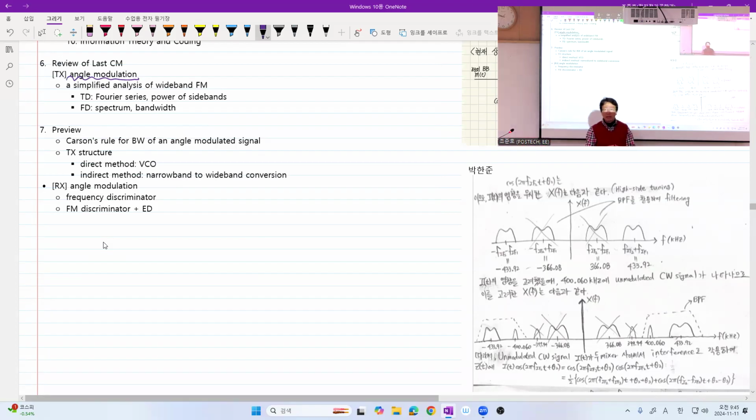The reason why our signals and systems course was so successful with Fourier analysis was that we assumed the system is not only linear, but also time invariant. You will see in some control courses, automatic control or some other courses on linear systems, if this is the set of linear systems, linear time invariant systems occupy a very small portion of it. Actually, linear time varying systems are very important. And your Fourier analysis tool sometimes does not work well. So be careful. What you learned in signals and systems was mostly for linear time invariant systems. However, you have to expand your knowledge to general linear time varying systems, where Fourier analysis is not omnipotent.